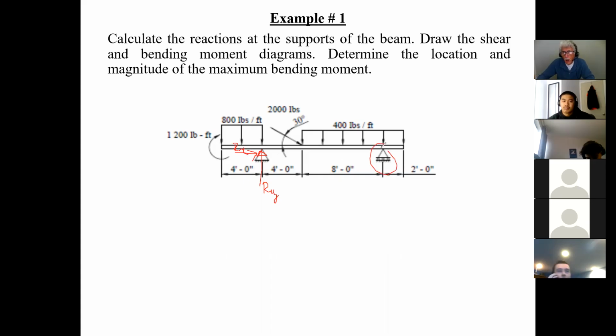And here, all I'm doing is not allowing it to move in this direction, and therefore I have only an Ry unknown. So that's one unknown, two unknowns, three unknowns. That means I can use the sum of Fx, the sum of Fy, and the sum of the moments to solve this. I should be able to use those three equations of equilibrium to do my analysis.